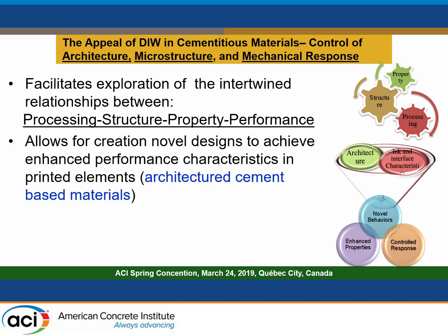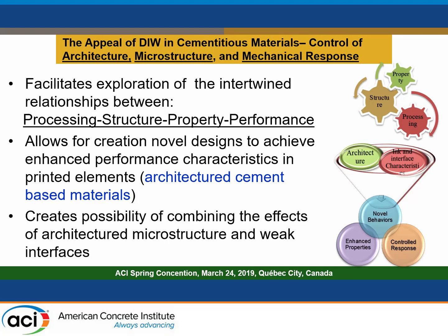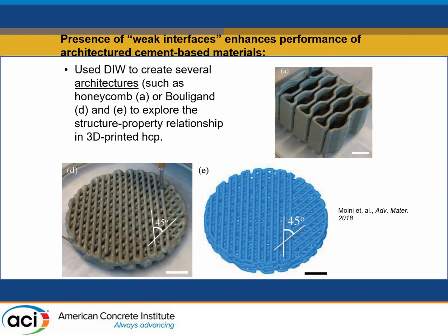So we are looking at architectural cement-based materials with control layout of the filaments, and therefore control layout of interfaces, and how they influence the properties. We are thinking that by combining those effects, you can actually change the behavior of otherwise brittle materials, and we have some results of that to share with you.